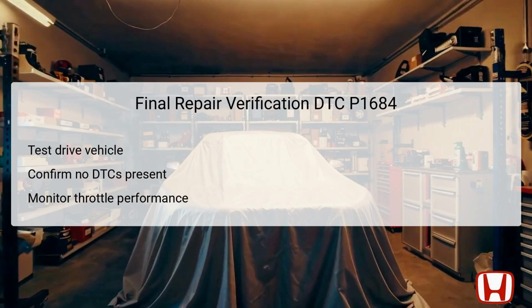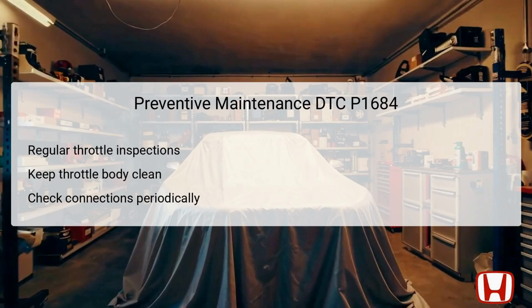safe operation henceforth. Preventive maintenance plays a critical role in averting potential issues associated with the throttle system, such as DTC P1684. Regular inspections of the throttle body and return spring assembly can help identify wear or damage before it leads to performance problems. Keeping the throttle body clean of carbon buildup and debris is essential for smooth operation, directly impacting the air-fuel mixture and the engine's efficiency.